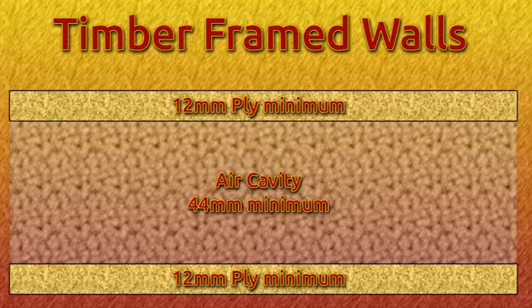The Australian standards recommend 12 mm ply, and I can now see why. Although the thicker the plywood, the better the insulation, it starts experiencing a serious diminishing return throughout the lifespan of a fire. I can safely say that following the Australian standards when constructing a timber house with respect to fire safety is the most cost-effective way of ensuring your property's longevity.